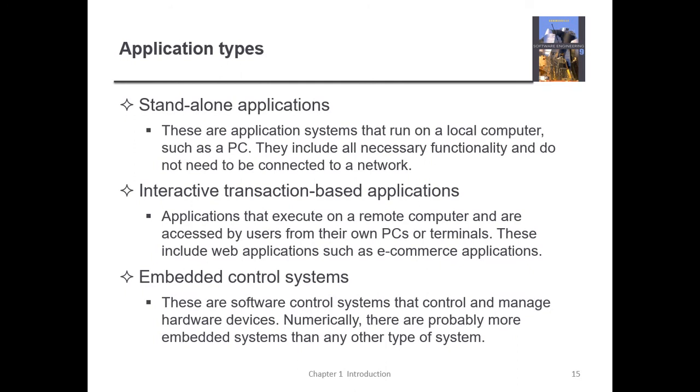Embed. Now, in English, to embed something means something is inbuilt inside another one. Put inside, to embed it. Now these systems, when we talk about embedded control systems, as you mentioned, we have hardware devices with software applications embedded or put inside them that will give instructions, and now these systems will work. An example are the automatic irrigation systems. These systems will use microcontrollers and microprocessors, very small ones, and simple instructions. And by use of sensors, they can do automatic irrigation. They can even sense the humidity of the soil and determine the amount of water to pour. So those are embedded systems.